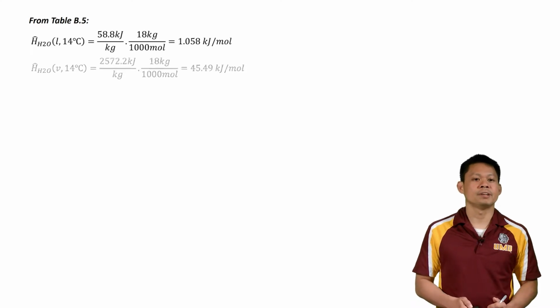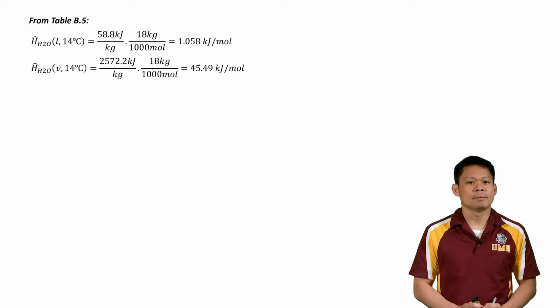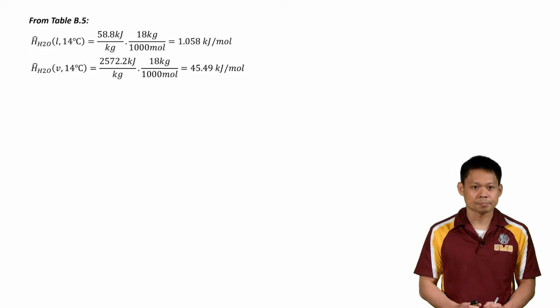We're going to do the same for the vapor stream at 14 degrees C. We know that this is in equilibrium with the liquid stream. We look it up and you see it's 2572.2 kilojoules per kilogram. Convert it, we get 45.49 kilojoules per mole.